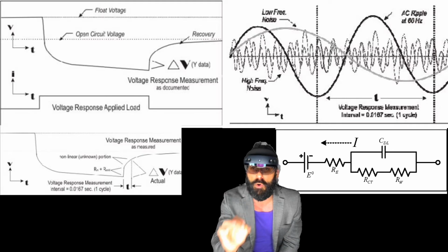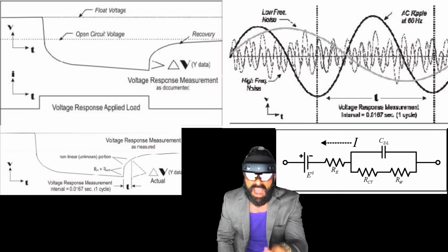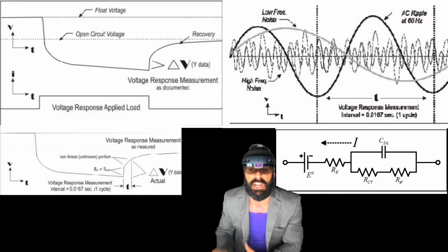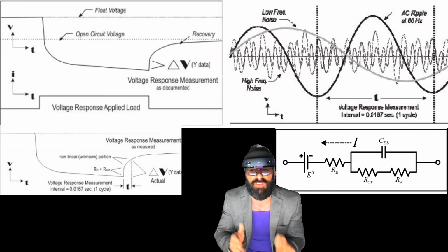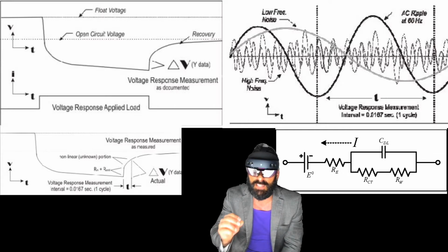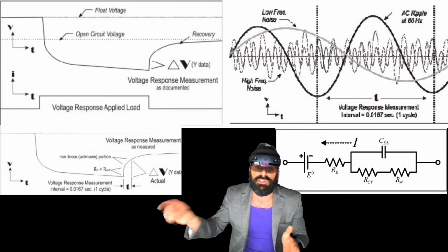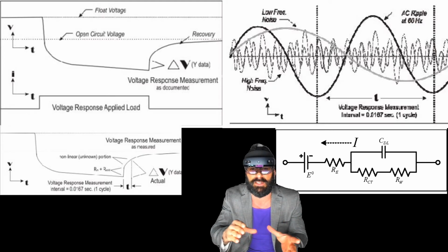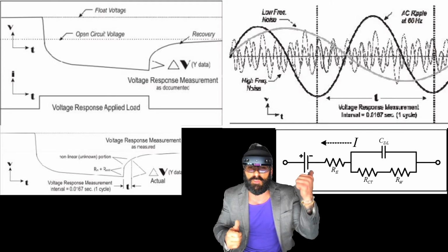And here's the important component of this. Every material of the battery reacts to a frequency differently. This is outside of capacitive reactance, right? But those sinusoidal signals are regulated at various millivolt steps to remain within the battery voltage of the battery. And this is kind of difficult generally if you're using a single frequency, but if you're using a lot of different frequencies, with a multi-frequency spectroscopy device, you can actually calculate multiple resistance values based on that Randles model that you see here.